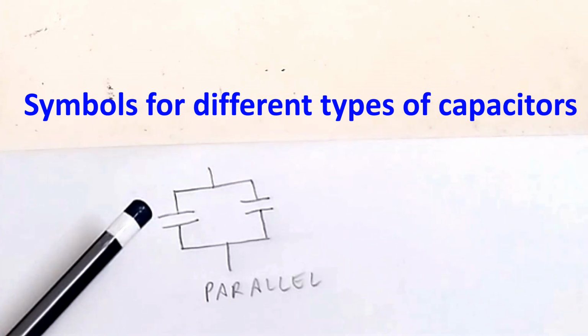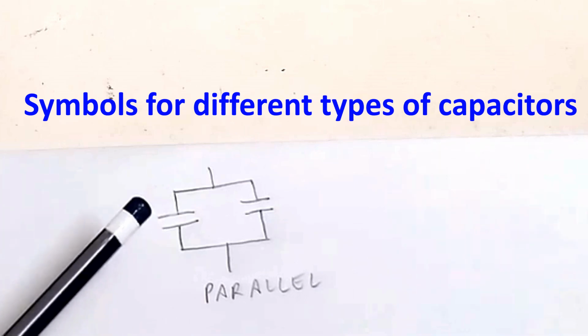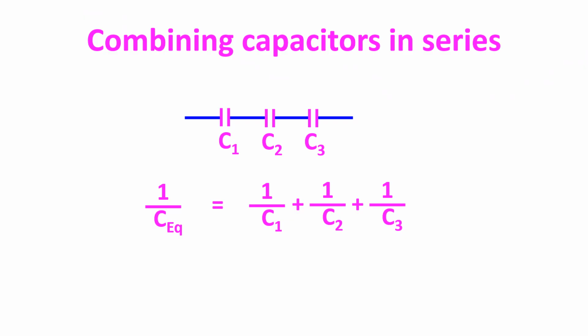If you combine in series, the capacity will be lower. While capacitors are combined in parallel to obtain higher value of capacitance as in filtering circuits, series connection is to achieve higher working voltage, though the resultant capacitance will be lower.